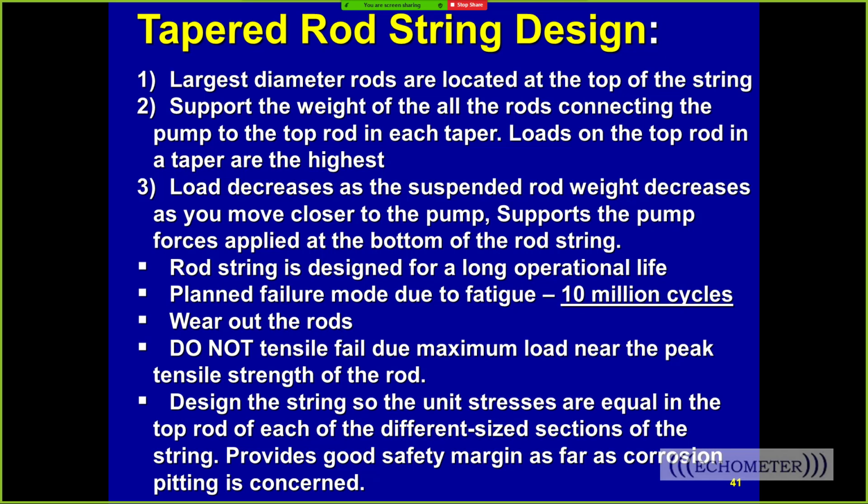But if you know your oil and water production rate and estimate the impact of the gas in the tubing, then you can make an adjustment for your tubing fluid gradient and get a really close estimate of the pump discharge pressure. Then, based on the height of the pump card, you subtract the height of the pump card from the discharge pressure. The height of the pump card is the fluid load divided by the plunger area, and that gives you the pump intake pressure. As long as there's not any mechanical friction that you're worried about, you're going to come up with a very good estimate of the pump intake pressure.